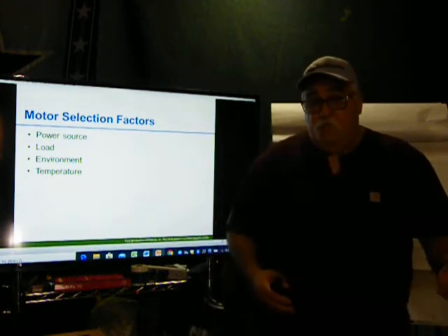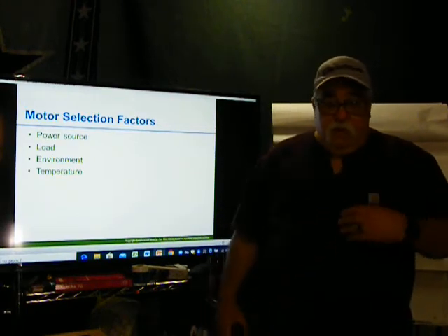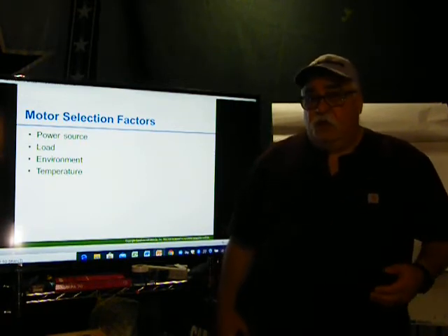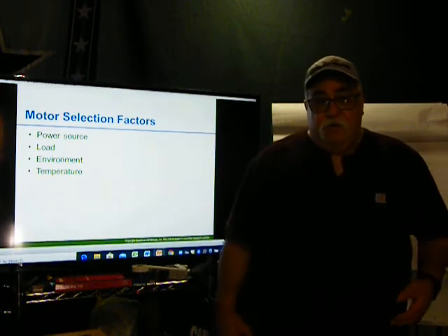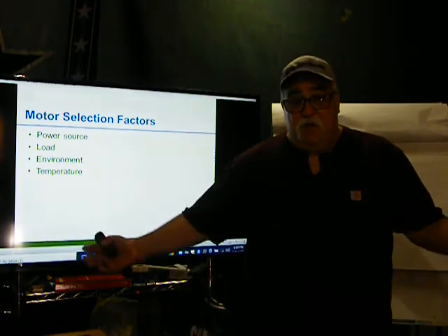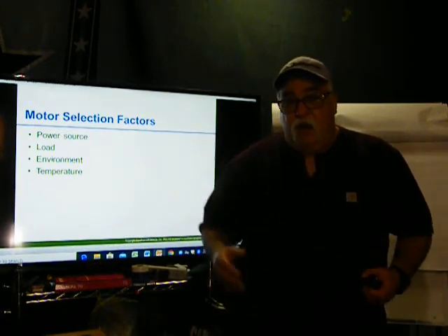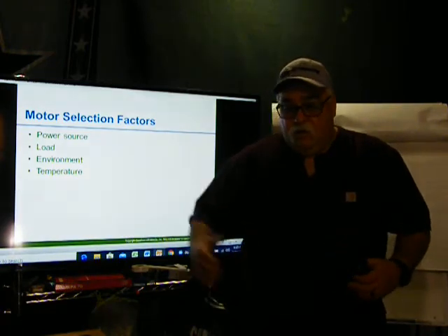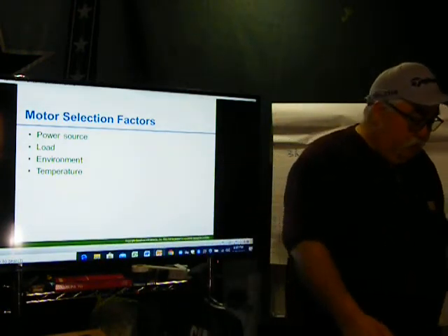In order to change that one motor out, we had to take the other motors off to get to that one. So I think it would have been better to spend the $2,000 for the encapsulated motor compared to the $125 motor, because when the machine's down, you've got 5 people standing around doing nothing for 4 hours till we get these motors changed and aligned, because it had 4 motors. It was like a conveyor belt type thing. So it takes about 4 hours to do it.